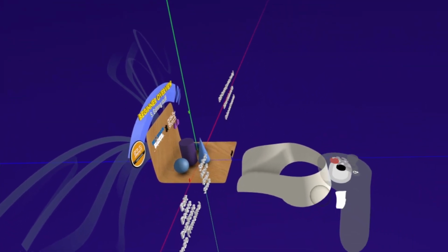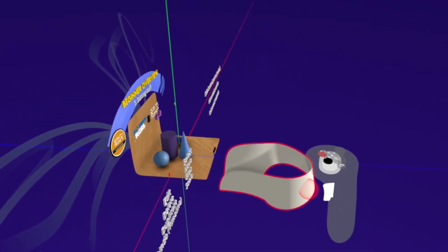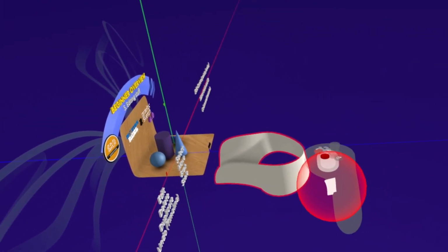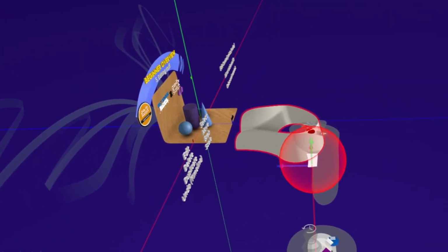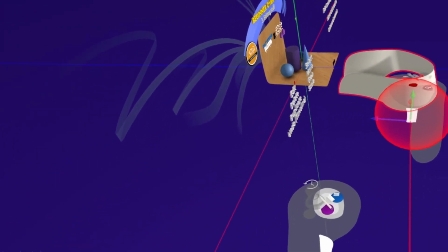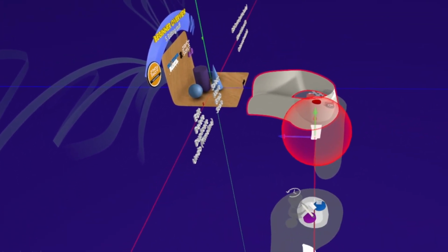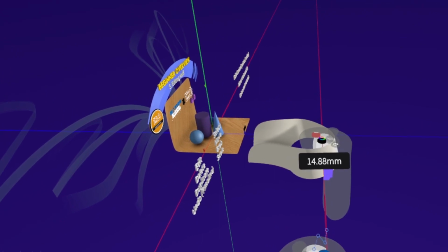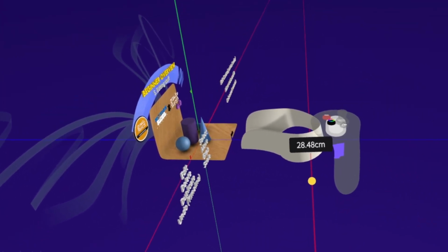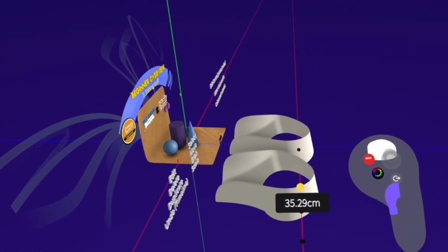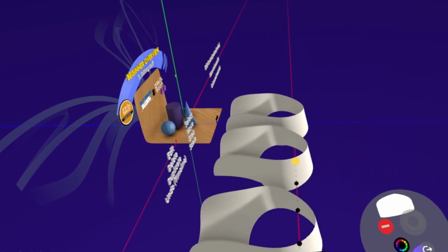The other way is by using the Smart Move tool. If I move my hand over this with the grab sphere, then I move this controller parallel to that in the direction of the axis, then it will line up like this and show the red line. When the red line is on, I can grab it with my grab hand and move it along this one axis. When I hit the trigger, it'll make a duplicate. And when I hit the trigger again, it'll make another duplicate.